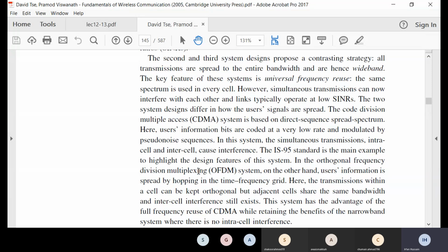And if I want to add frequency diversity, then I will make sure that my time frequency grids or boxes are further apart, in different coherence bandwidths. If you remember the L and the N_C over L and all that, so that you can also get frequency diversity gain.